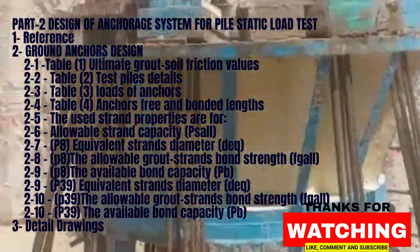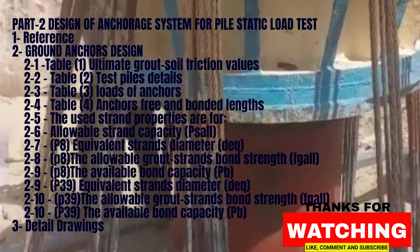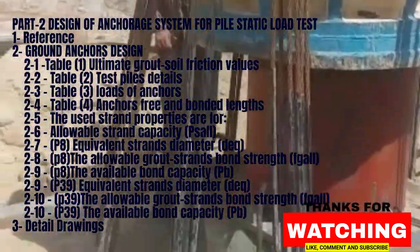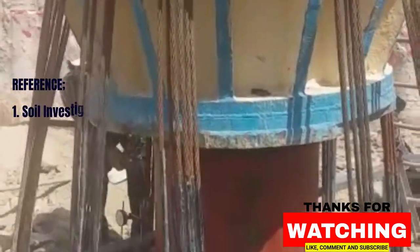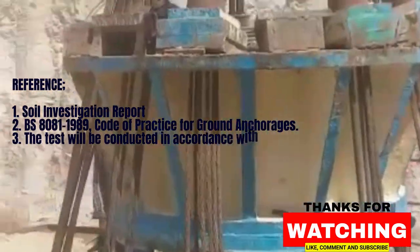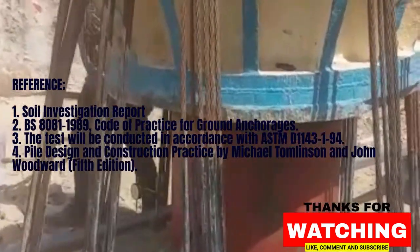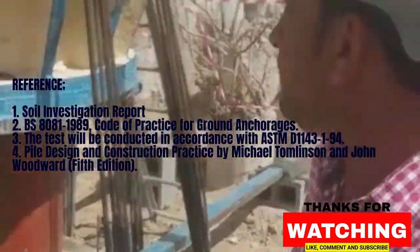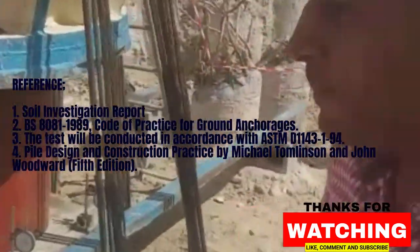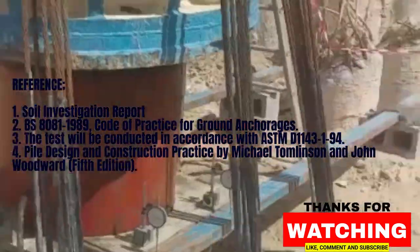For the structural design, this is going to be the design of the Anchorage system for static load test. For references, first we have to have the soil investigation report, and for the code I am going to use BS 8081 1989, code of practice for ground anchorage.